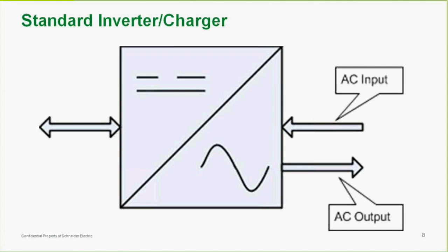We're going to mess with this theory in a little bit when we talk about AC coupling, but for now, just leave it at this. So the battery terminals in an inverter charger are bidirectional. The AC input right now is an input only, and the AC output is an output, which, from our previous slides, is a voltage source. So it's a battery-based output.